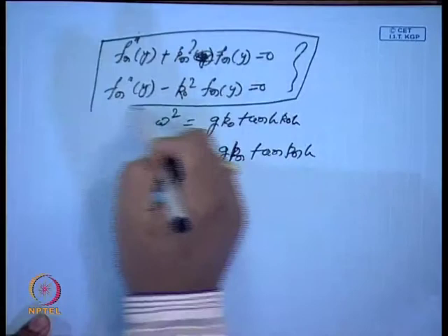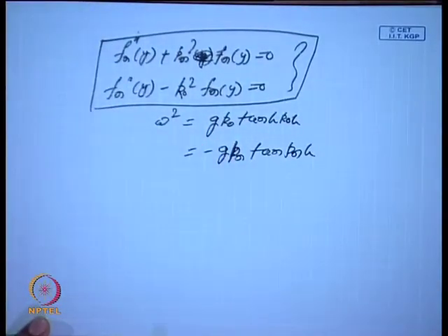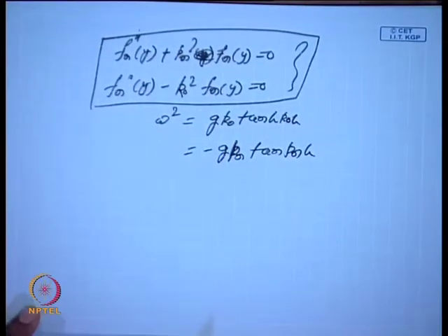These are all standard Sturm-Liouville problems with two-point conditions, because they satisfy the free surface condition and also the bottom condition. We have simplified to the standard ordinary differential equation, which has basically come from the y component of the Laplace equation.